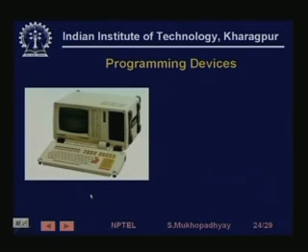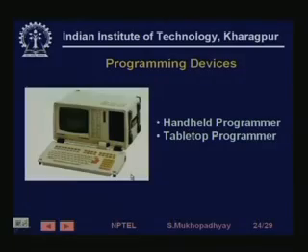Then you have to have programming devices, and this is a typical programmer. Programmers are of two types. Either they could be handheld, which you can take to the shop floor and directly program the PLC, or they could be tabletop, which are of higher capabilities, where you actually develop programs offline and then go and just load it there, because these have very good program development environments also.